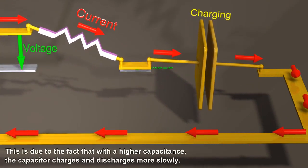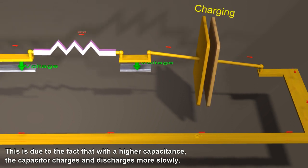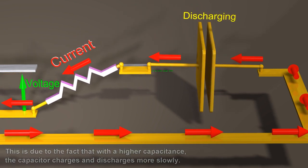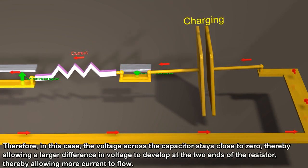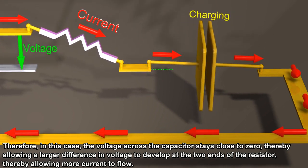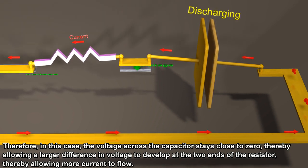This is because with a higher capacitance, the capacitor charges and discharges more slowly. Therefore, in this case, the voltage across the capacitor stays close to zero, thereby allowing a larger difference in voltage to develop at the two ends of the resistor, thereby allowing more current to flow.